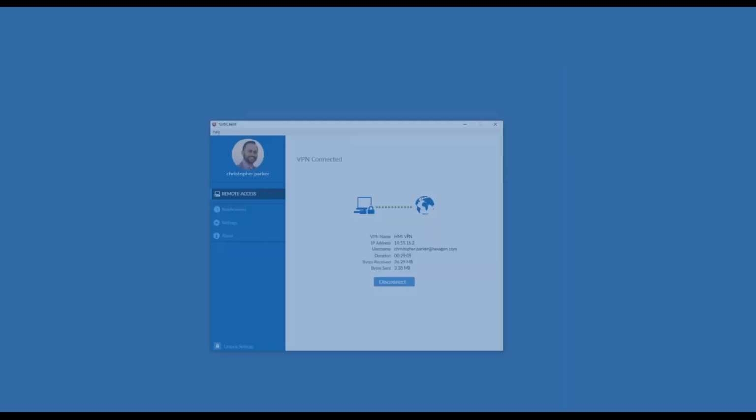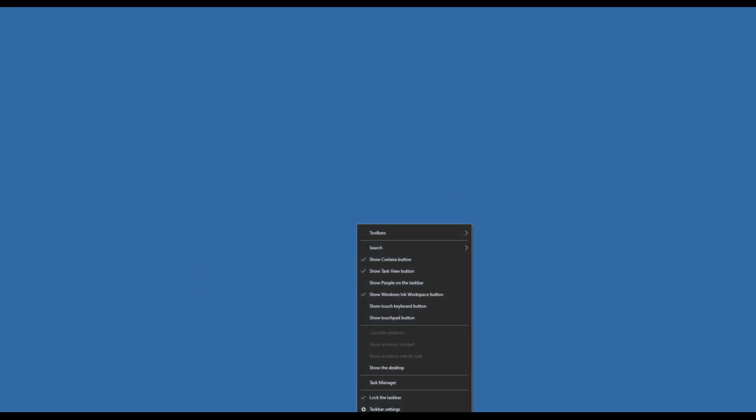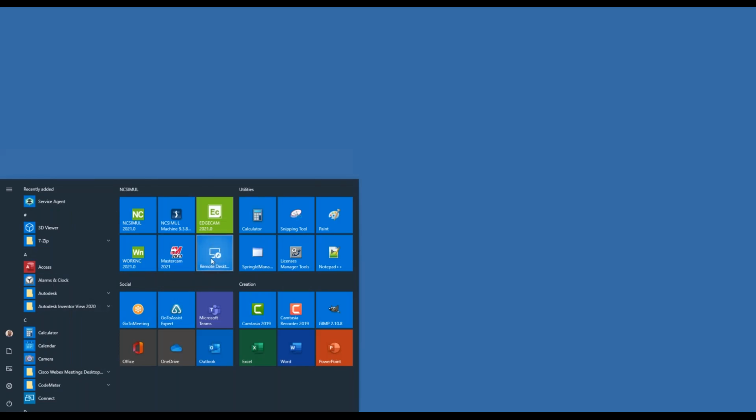And then the second question is, will you be demonstrating how the ZOLLER presetter can capture a tool profile? So the ZOLLER presetter, I don't think so, but you can answer maybe, Cedric. Yes, that is possible. Most likely with the tool presetter and ZOLLER, tools are automatically captured. So if you were to take a measurement within the presetter, you don't even have to push a button. It's automatically synchronized to all the measurements you do on the presetter, and if you do have TMS, this will be immediately captured in the ZOLLER TMS, and you will see those measurements. And I will show that in my live demo on how this will look within the ZOLLER database.